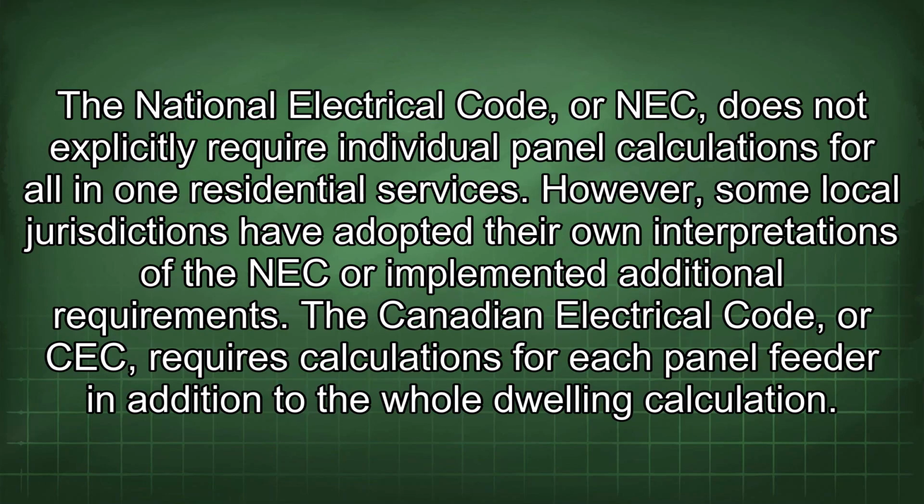The National Electrical Code, or NEC, does not explicitly require individual power calculations for all-in-one residential services. However, some local jurisdictions have adopted their own interpretations of the NEC or implemented additional requirements. The Canadian Electrical Code, or CEC, requires calculations for each panel feeder in addition to the whole dwelling calculation.